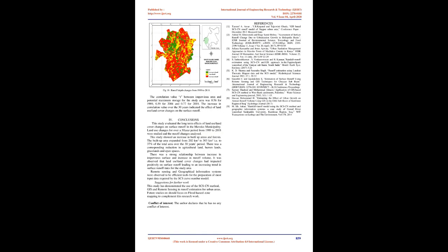The observed trend in runoff volumes indicates that in the future, built-up areas will be the predominant contributor to surface runoff. Because built-up areas have greater runoff than other land uses, designs for drainage systems should factor in the increased runoff in the design life of the systems. Fig. 9. Runoff volume changes from different land use / land cover types in the study area in 1989, 2004 and 2018. Spatial runoff changes.